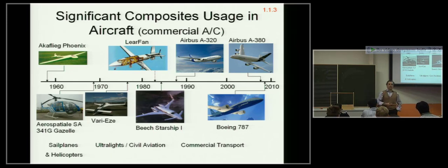This was the first airplane to get certified in the late 80s, the first all-composite airplane. It was not a success in the market because it fell short of its projected targets in terms of performance, range, and speed. And that has a lot to do with the aerodynamics, increased drag, and a few other problems. For example, if you have a relatively long beam and you decide to hang at its tip a mass, those of you who remember the dynamics, you realize that it doesn't help very much on your frequency response. And in fact, to hold this winglet onto the wing, you will need what's called a fitting, a three-dimensional structure that will hold the two together.